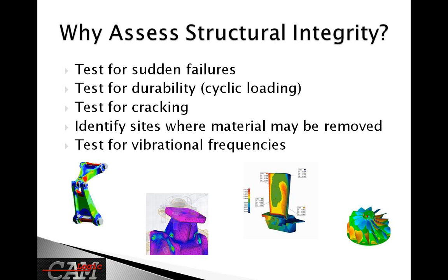On the positive side, when the structural integrity is assessed, then you can see areas of high and low stress. And in those areas of low stress, it's possible to remove material and still maintain structural integrity. So that would be a technique to be able to reduce weight of a component while maintaining performance. When doing so, it's important that a multitude of load cases are considered to make sure that an area that may have low stress in one load case may not have a higher stress in a different load case. So that's why it's important to look at all the load cases of interest for that component.